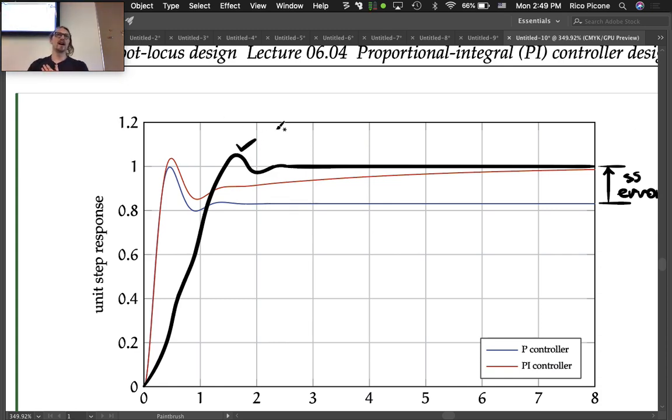They went with this design where it's going to take a minute to respond. But if they were to go the other direction and say, we want that initial quick response, then right when you hit that hill and started to drop speed, you'd rev up quickly and get close to your set value. You'd get up to like 58 really quickly. But then it would take a little while to actually get to 60, a slower response to get that last steady state error out. So you might go to like 62 and then 58 and bobble, instead of being slow but exact.